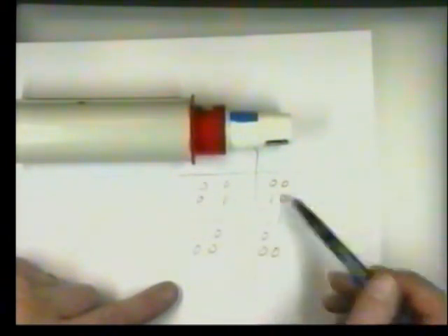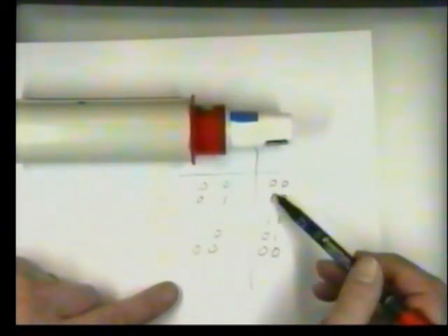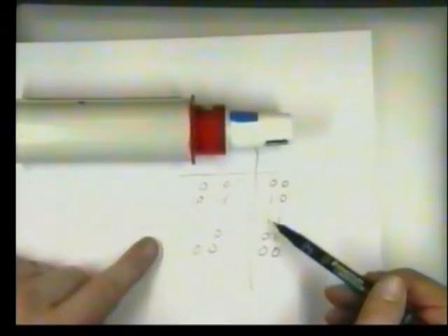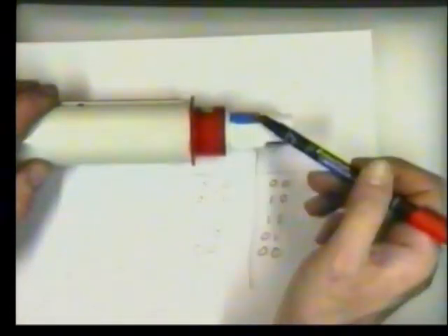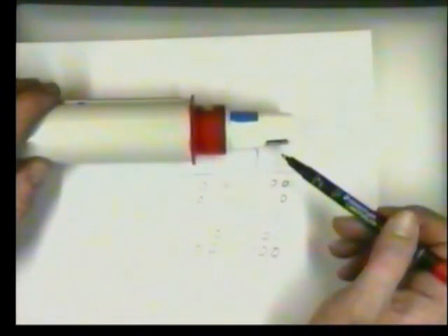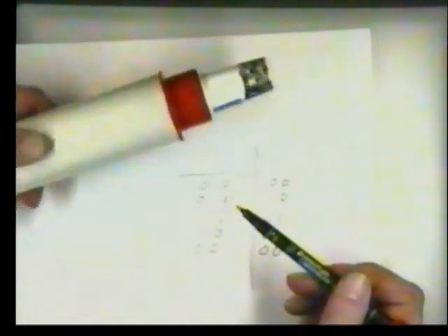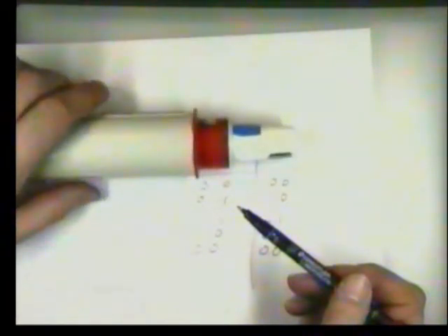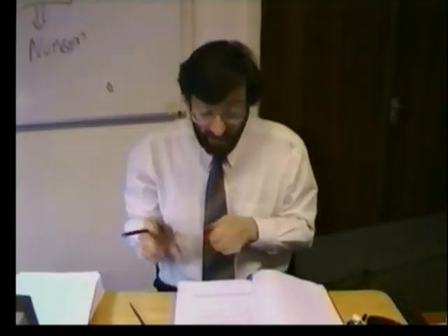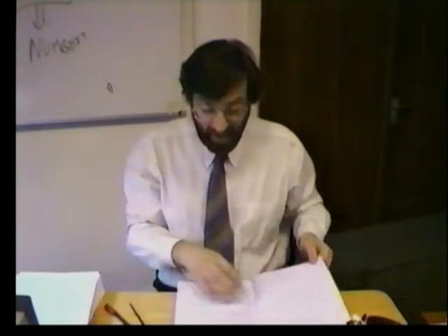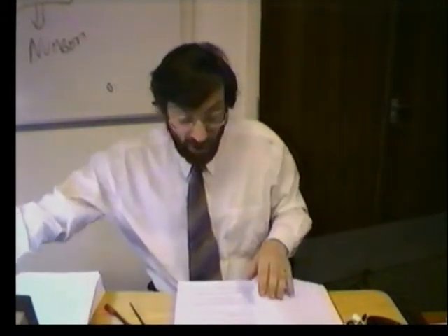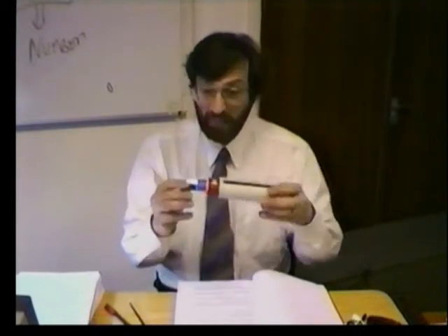00 goes to 01. In this one, 00 always goes to 10. So by adding the second marker, not only are we able to determine how much it's rotated, we also know what direction it's rotated in as well. And this is known as quadrature encoding.